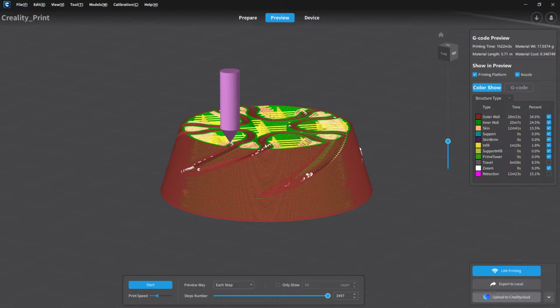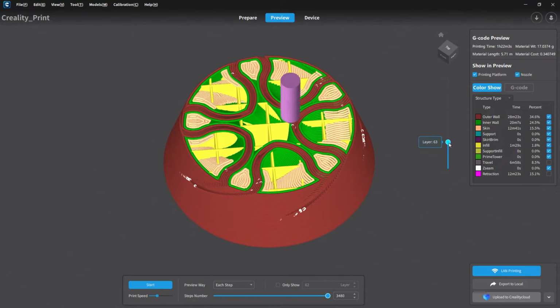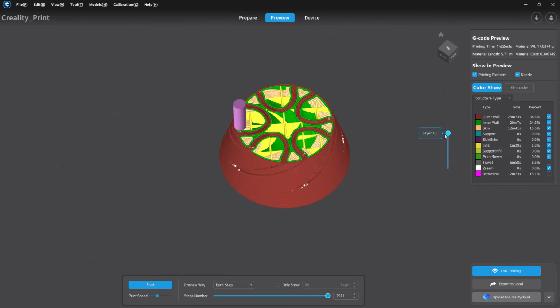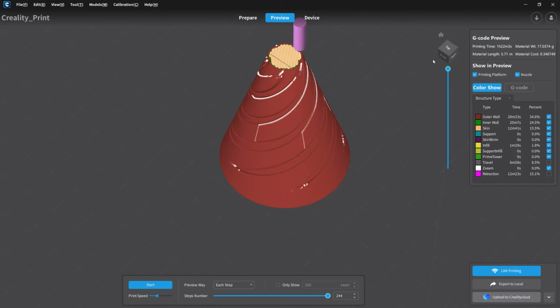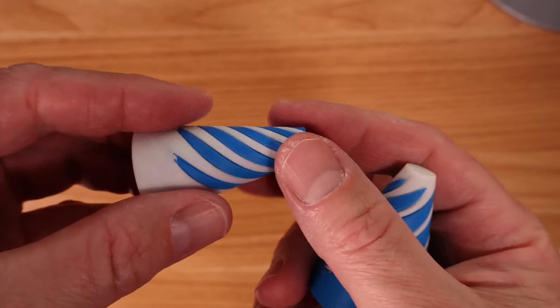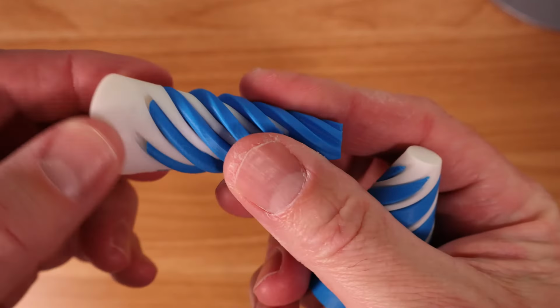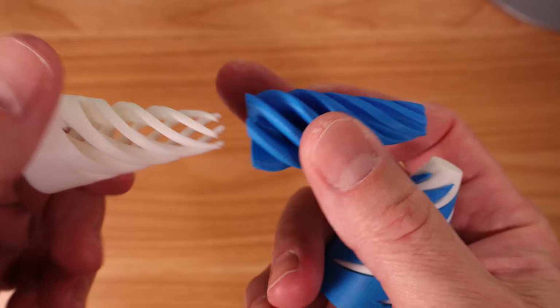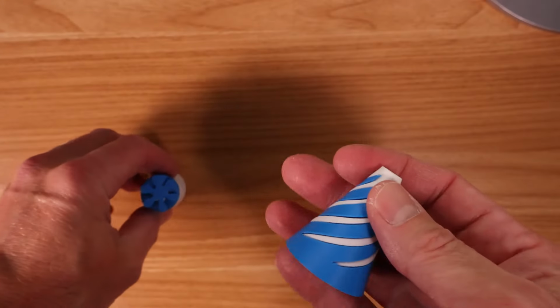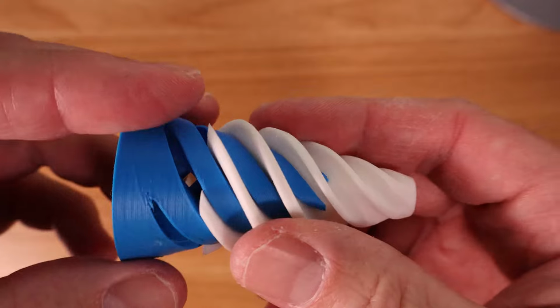But again, this is very much dependent on your printer. So if you happen to try to print in place like this and you have a problem, then it's going to be nearly impossible to break these pieces apart. But there is enough of a gap if you're using something like 0.4 or 0.5 millimeters. So that's it. That's the basic process. And it's really fun to play with, but keep in mind if you are making these for, let's say, your kids, there is definitely a noise that happens when the layer lines rub against each other, just because of the nature of the print. So while it is a nice fidget toy to occupy some idle hands, the noise may be a little bit too much to handle. So just keep that in mind if you are handing these out and you're using an FDM.